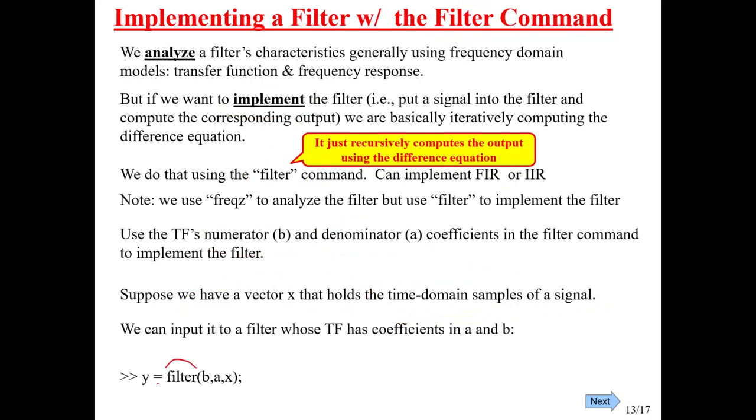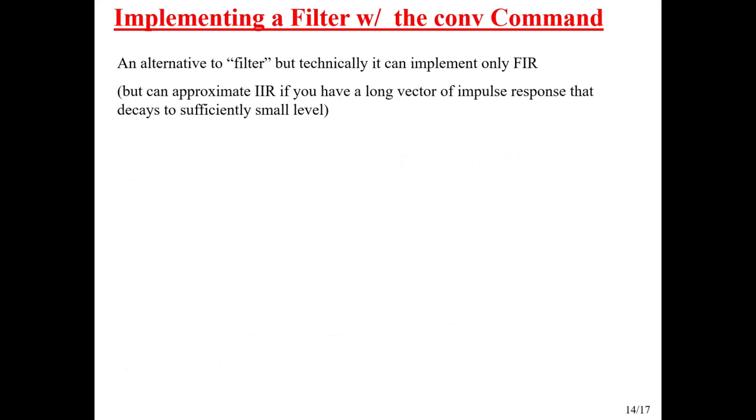Literally, this filter command does nothing more than recursively solve for the output samples, given the filter coefficients, and given a stream of the input samples. That's all that it does. So notice lowercase x, okay? Time after time, I see a handful of students every year thinking that they implement a filter by multiplying its spectrum times the frequency response of the filter, or that somehow we put a frequency spectrum in there. Nope, that's not what we're doing. Okay, so keep that in mind.